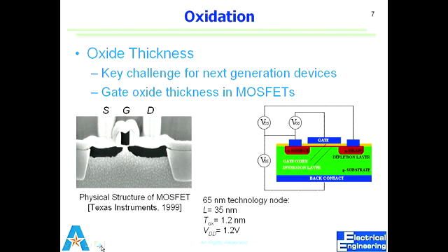Since the whole physics of devices is based on oxide thickness and the behavior of that insulator, we convert these other materials into EOT, equivalent oxide thickness, and use that in measuring the behavior. And that is one of the features which defines the node also, what node we are at.